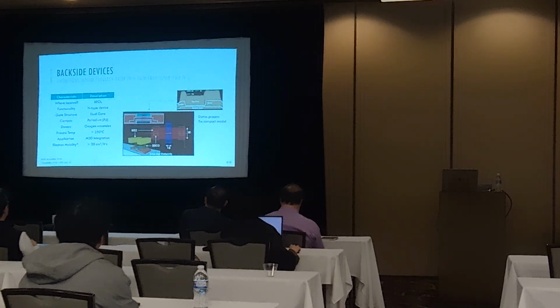Transistors on the backside, right, between the metal lines. In fact, this is work by Jason Snyder, who is working with my colleagues at Georgia Tech on open manufacturing of the device. It's called an IWO device, an amorphous indium tungsten oxide thin film transistor. You can again create these in between metal lines, so it's a back-end-of-line transistor.